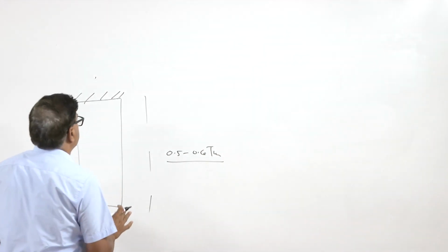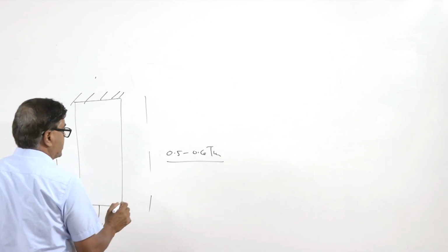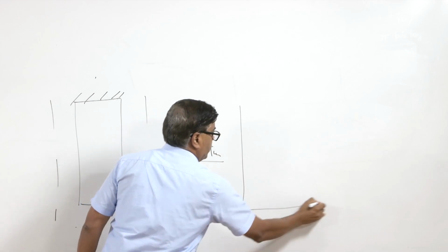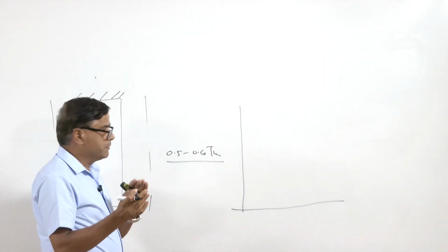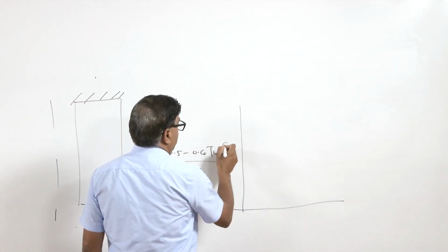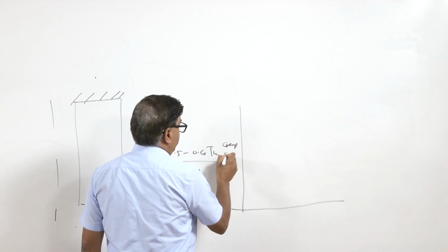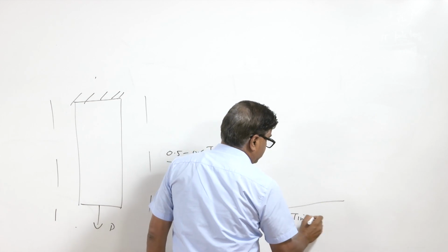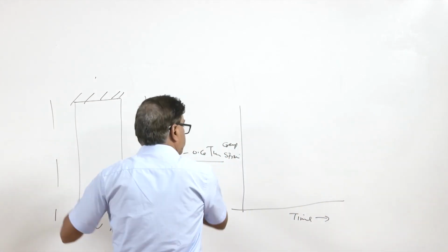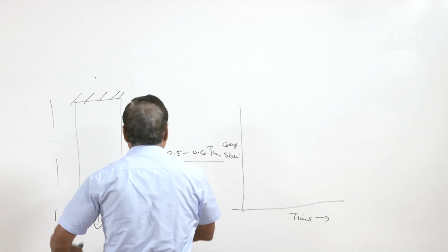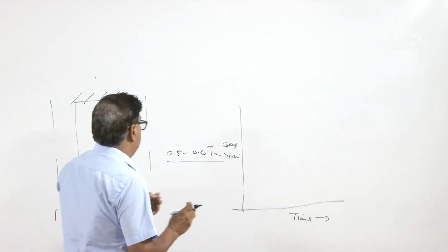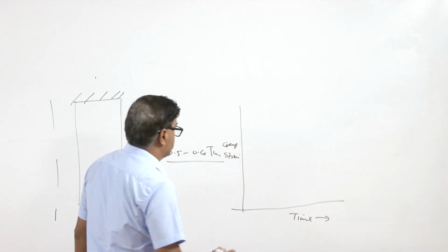So, with such a high temperature exposure at a constant load, there is a continuous increase in the length of the sample, which we quantify in terms of strain. This strain we can call the creep strain, and the creep strain increases as a function of time at a high temperature. So, there is a continuous change in dimension of the component during the exposure at a high temperature.